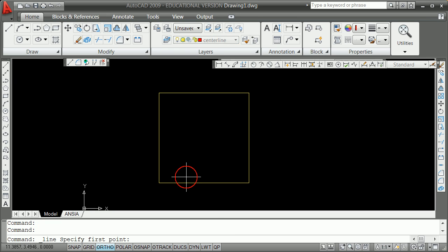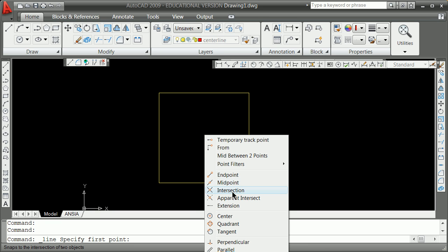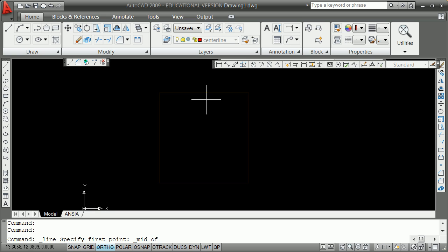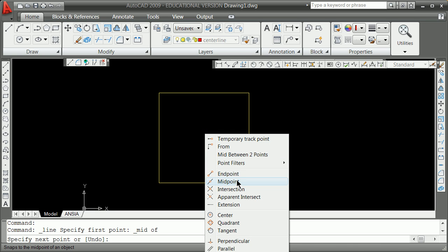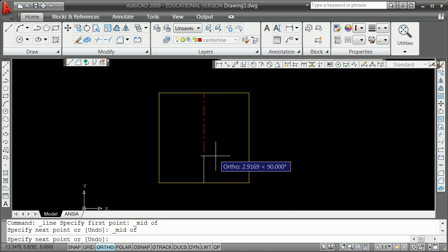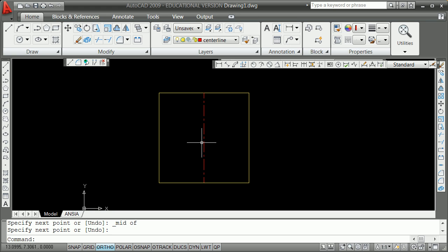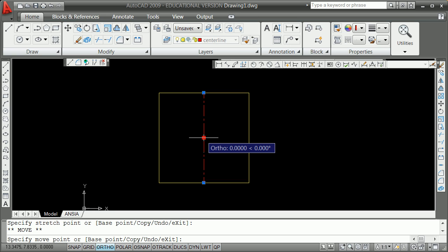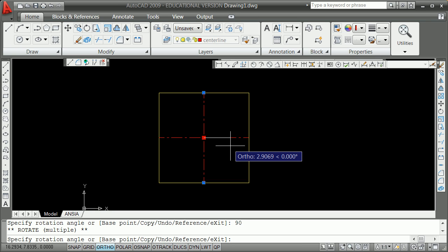And for now, I'm going to just draft a center line from the midpoint of this line down to the midpoint of here, and I'm drafting on the current layer center line, realizing it's always not a bad idea to go left click, spacebar, C for copy, 90 degrees, and now I've got two center lines going back and forth there, which I can draw my other center line, strong base line, strong base angles.